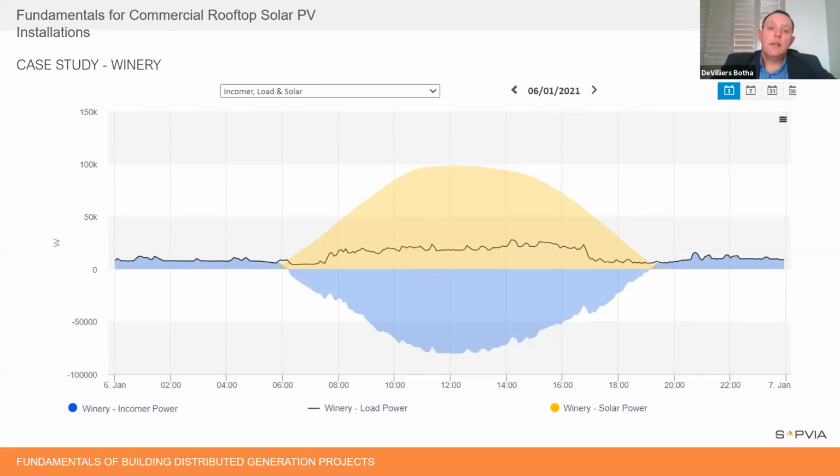So as Greg also said, you engage with your municipality, and in this instance, there is a feed-in tariff where you could then plug in the feed-in tariff according to the data you then have of this client, and then look at the solar generation and see how, over a period of a full year, you optimize and design the system. So if you've taken a harvest load, you would have said this client needs a 700 odd kilowatt system, which would have been totally oversized for a feed-in tariff where you only get paid 52 cents. But if you went to a 200 even for the winter load, the July load, you would have also had the same problem. So that's why it's important to take a full consumption, and the more data you get, the better, and then build the system according to that.